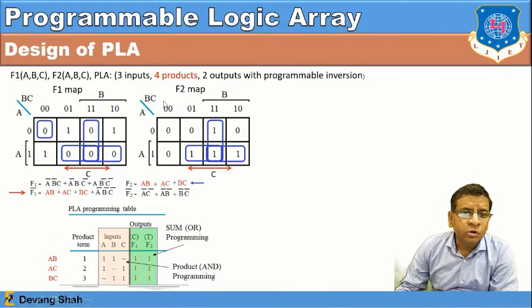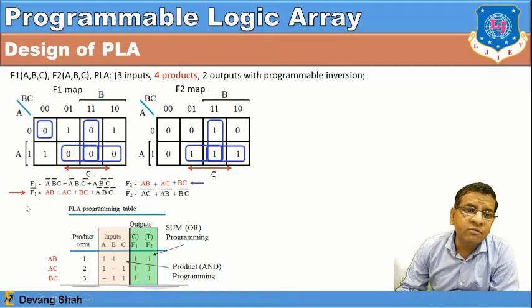So there are a total of four products, like F1. That's what is available from this particular group of zeros. In a way, this is an inversion kind of platform where, instead of taking ones in a K-map, I'm taking the zeros in a K-map. So based on those zeros in the K-map, you'll have F1 equal to A dash B dash C plus A dash B C dash plus A B dash C dash. So based on that, you can take a kind of inversion of F1.